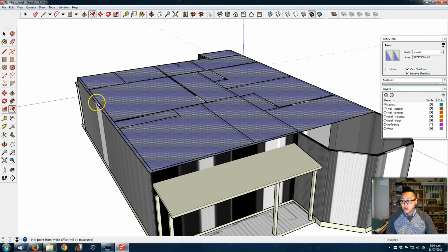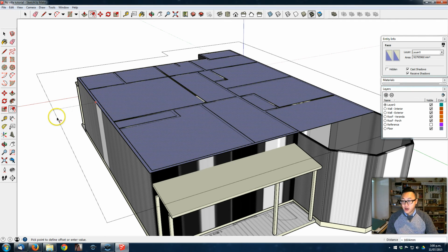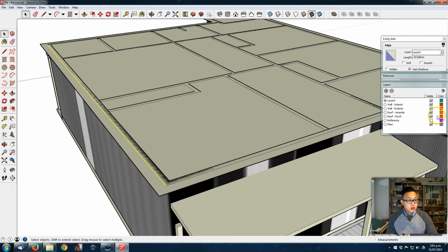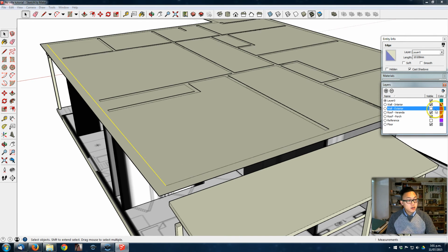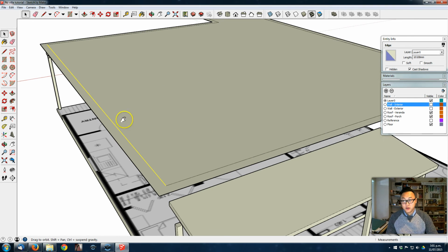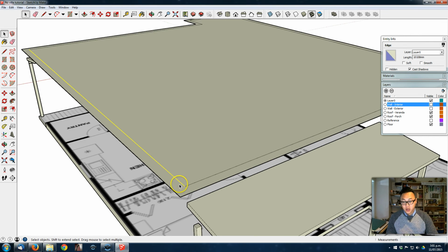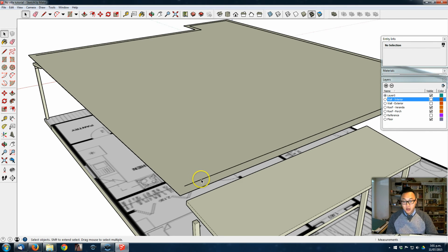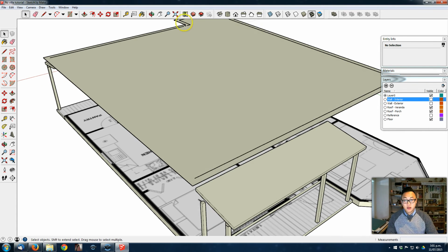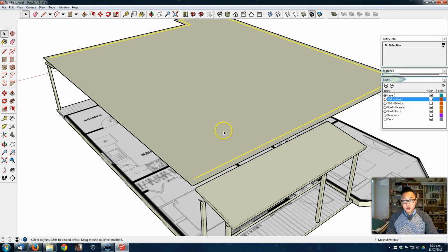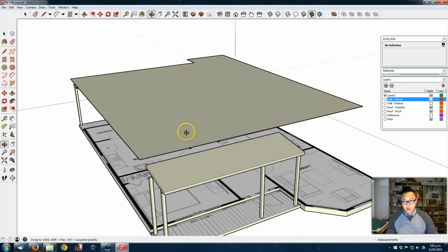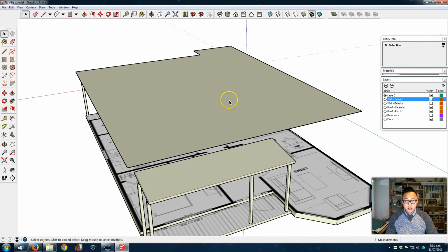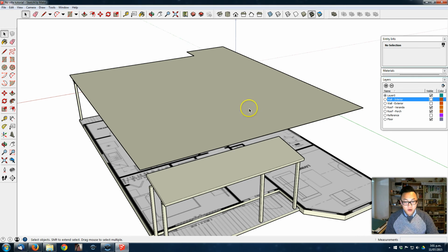So here we're gonna use the offset tool, bring it outwards 200, and let's hide the exterior wall and interior as well, so we can select the, so you see you get the original line, and because we don't need that anymore, we just delete it, and because we have that line there, we just double click and delete that as well. So that's gonna be the surface of my roof, and now I'm gonna create the profile.